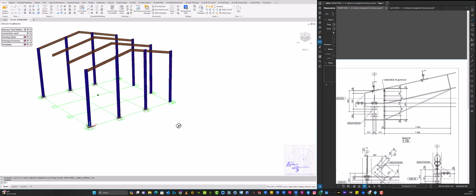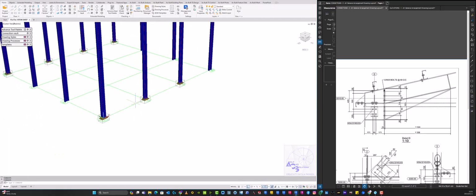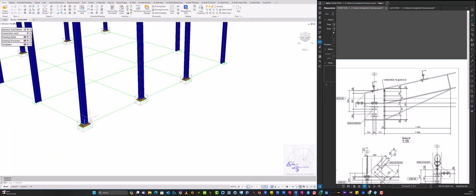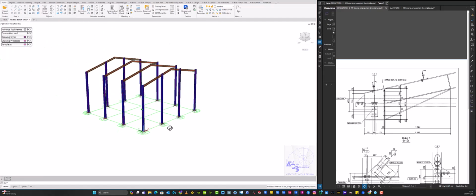All right, then from there, we just mirror this to the other side, or you can copy it to the other side. It depends on what you want to do. Since we used a copy, let's mirror it this time. So now our base plates. Remember the propagate command: just select the connection box, right click and say propagate. All right, so the base plate has been created.